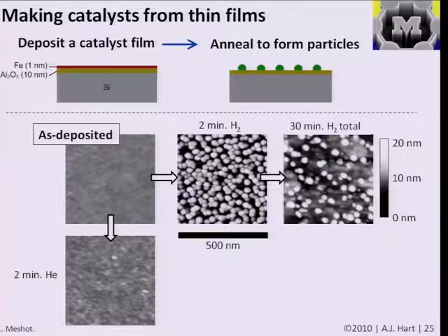And for example, if we keep the substrate in hydrogen for a longer time, we would see that the particles will evolve in size. They will get larger because of diffusion from the smaller particles to the larger particles, and also because of the permeability of the substrate, you'll also lose some material with time. So later we'll get to see how this relates to how the sizes of the nanotubes will change versus time, and how the density of the film might change as the growth process proceeds.